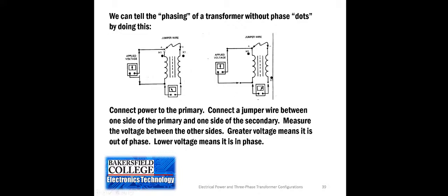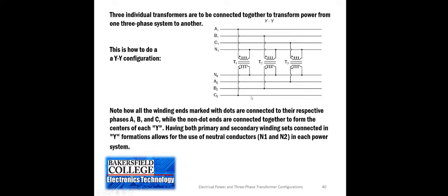So remember, you see the pluses up there at the top, and then this is a plus and a minus. That is the polarity of the input AC coming in, stopped at a moment in time, compared to what the polarity is at the output at that same moment in time. So in phase means that the polarity is the same on both sides. Out of phase means the polarity is opposite when you compare the two sides.